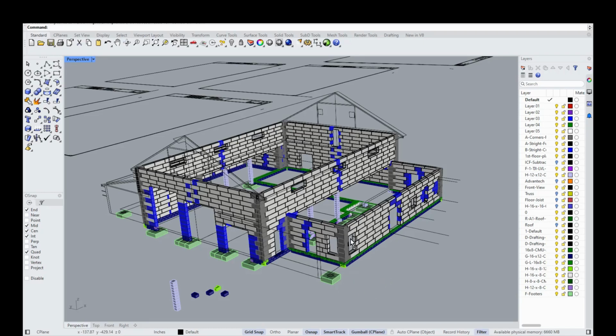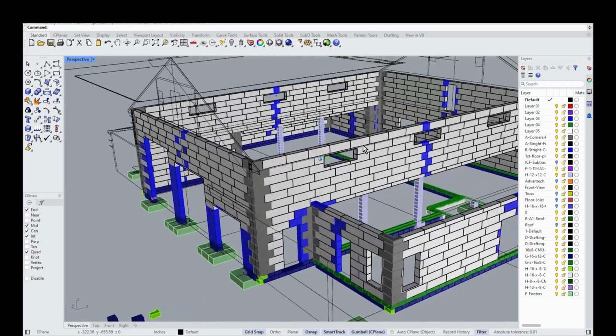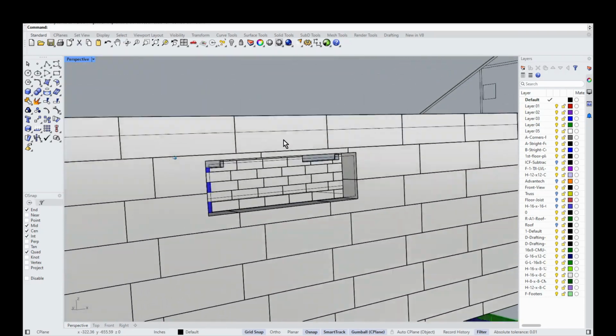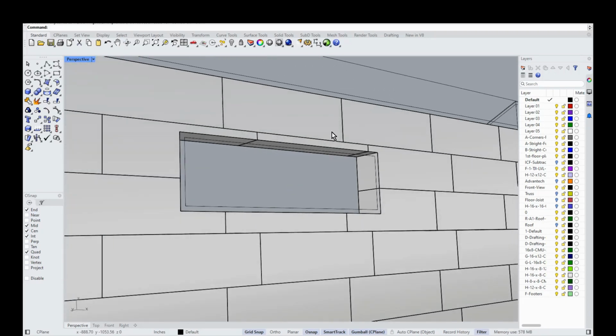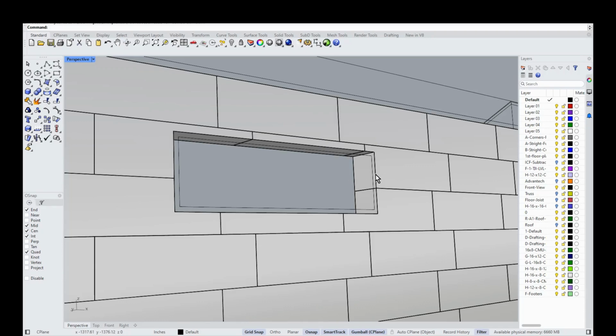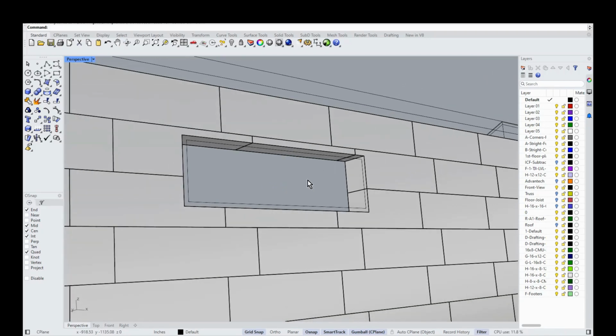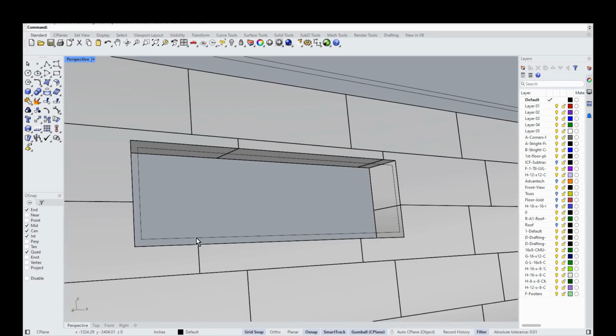And these blocks aren't quite like cinder blocks. You want to get them off the pallet, put them in place, and pour them, because it is styrofoam. With ICF, I should also point out that they'll put bucks around the whole perimeter, usually a 2x12 ripped to the width of the ICF block. I can put some pictures of this in a later video, and put it across all the sides.